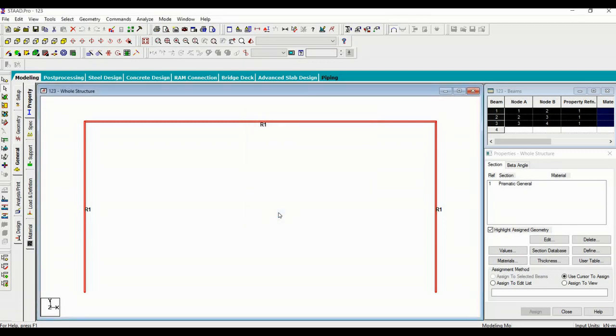See, while assigning a material property, I mentioned one thing. If they give the dimension of the beam, that is, if it's a rectangular beam, directly go to the Rectangle option, then enter width and depth, and that is fine. I mentioned it like that, correct? So if the beam cross-section dimension is given, these things are not required.